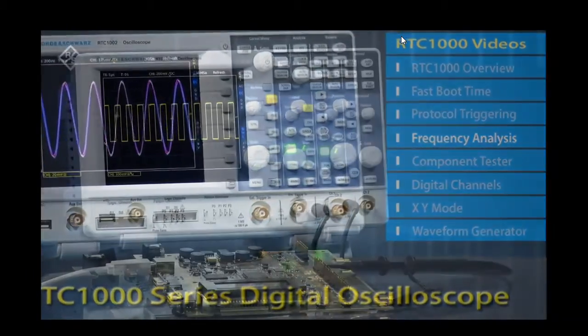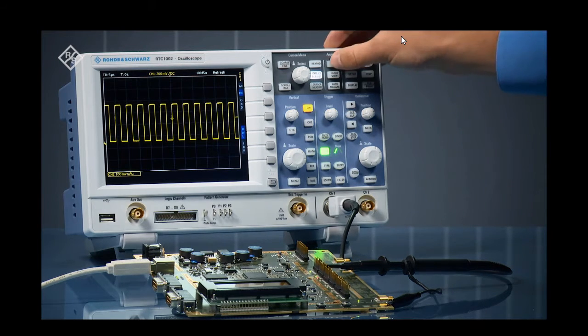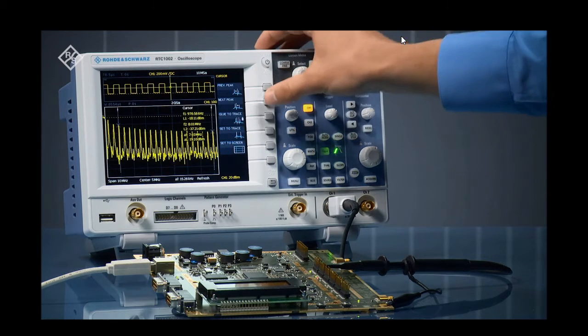R&S RTC1000 series oscilloscopes include frequency analysis as a standard feature. Do you want to ensure that unwanted frequencies aren't coupled into your system? Or do you want to look at frequency components of your signal? Just press the dedicated FFT button to see the fundamental frequency and multiple harmonics. For optimal visibility, both time and frequency information are shown in separate windows. And finally, for faster analysis, cursors automatically identify peaks.